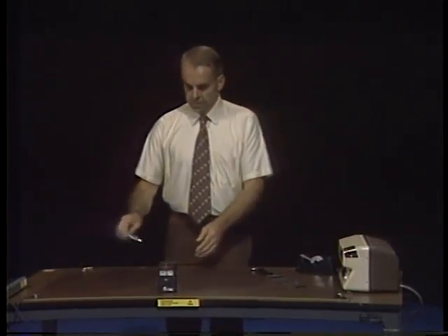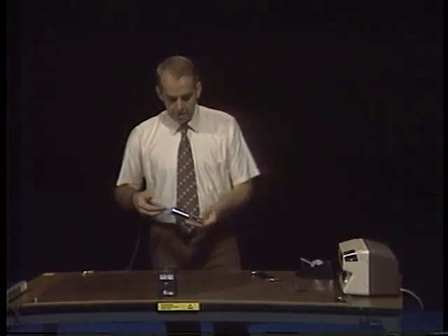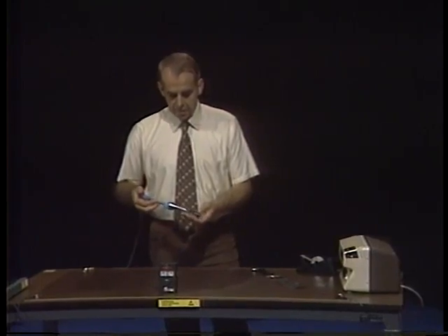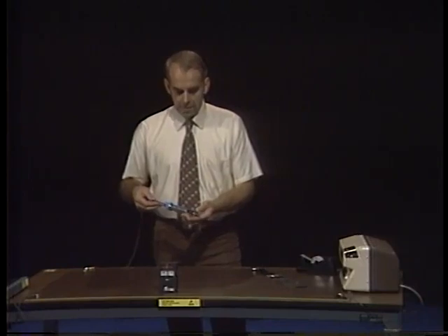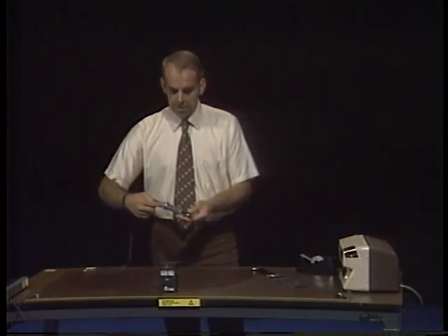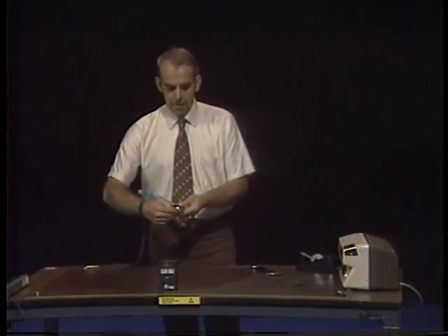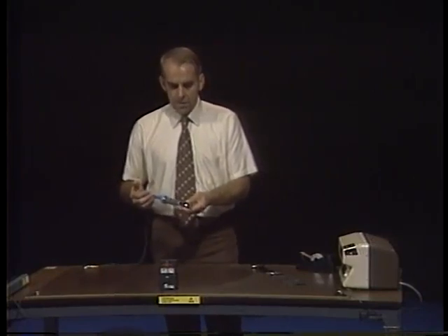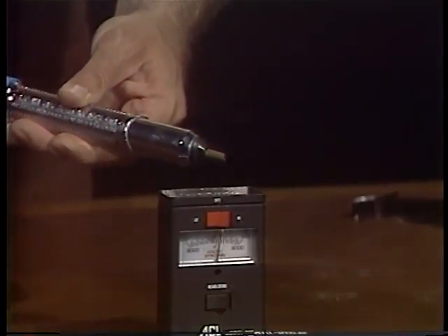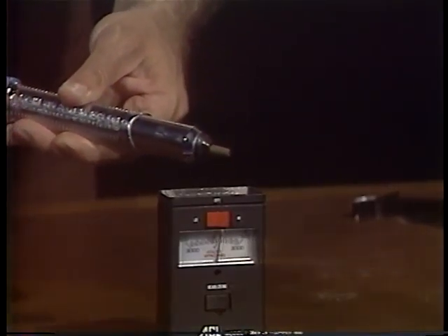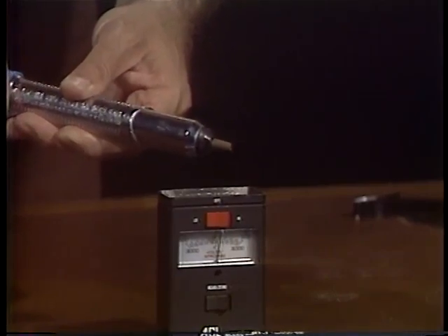The fourth weapon in our arsenal of tools is the anti-static desoldering tool. Here is an example of one. It differs from the previous one only in that it has a metallized barrel inside and out and a metallized tip. When this tool is held by the operator, you can see that there is no change to the reading of the meter. Even when the tool is triggered, nothing happens because all the static charge is eliminated.